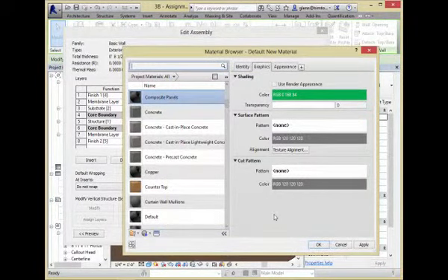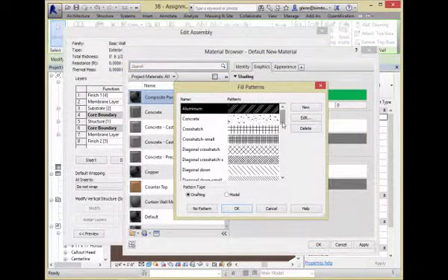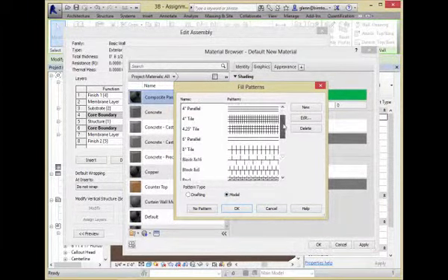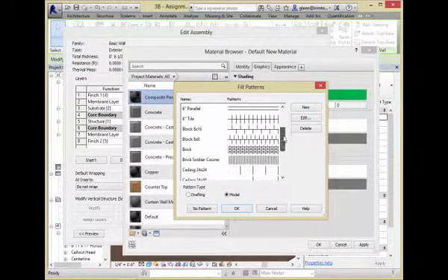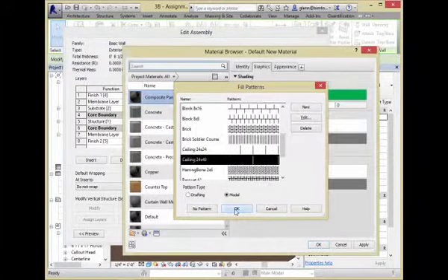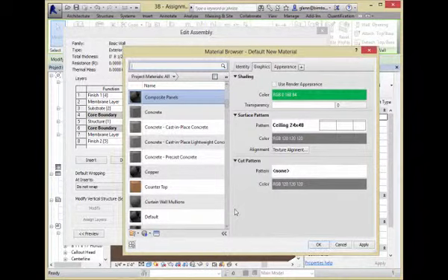Okay, we have the notion of a surface pattern. That is really what it should look like in 3D views and in elevations in terms of the line work that's on top of it. And we could choose a lot of things in here in terms of patterns. They have some patterns which are drafting patterns. I like to use model patterns. Model patterns scale. So if I find like 24 by 48, although it's a ceiling pattern, it'll apply the same basic hatch pattern to the walls. So I'm going to get something that's going to look like 2 by 4 grids, over that grid color.